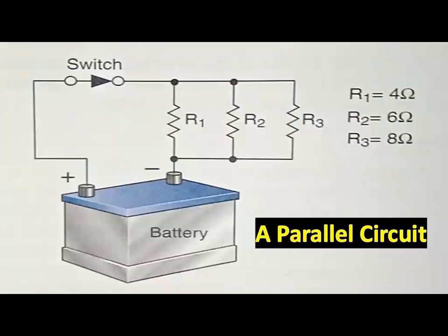In a parallel circuit, each resistance is a separate path for current flow. These facts may be summarized regarding parallel circuits. Each load has a separate path for current flow. The amount of current flow through each load depends on the amount of resistance in that part of the circuit. Equal full source voltage is supplied to each load and equal source voltage is dropped across each load. The total resistance is always less than the ohm value of the lowest resistor in the circuit.